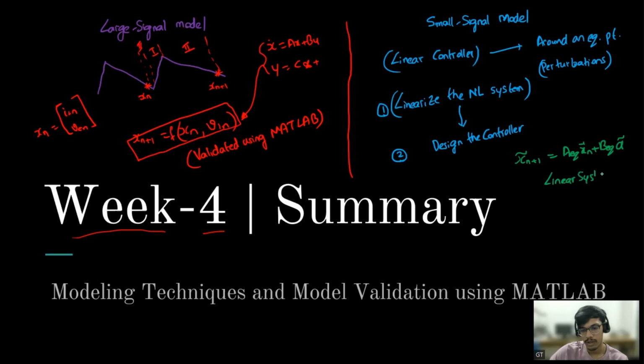Sir, during perturbation, won't there be an input voltage perturbation? No. One assumption we have considered is that the input voltage is constant, so V in perturb is 0. But if you consider that the input has a perturbation, then you will get another matrix multiplying V in perturb, which makes it complex. But for whatever converter we are running, we assume that the input is constant, more or less. V in perturb is considered 0 because V in is constant. Now we have linearized the system.